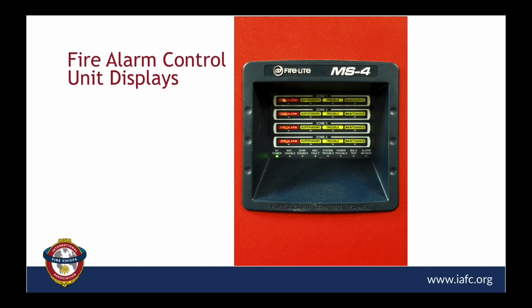And then you're going to see this maintenance light that I briefly mentioned. This is another manufacturer's option. It's not code required, but it's a good feature in that that light will illuminate when there is a code required need for maintenance, or that there's something in its diagnostics that's saying, I need some help. We know that fire alarm panels need to be inspected and tested at least once a year. So that light will light up annually for sure, and maybe more if it's necessary, to let people know that maintenance is required. But you see the trouble light here is going to give you your trouble conditions and the like. So this is a maintenance only.